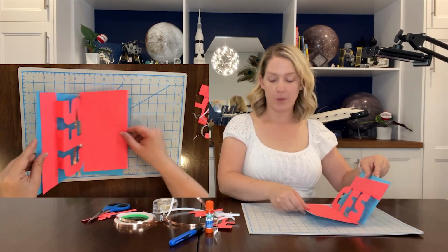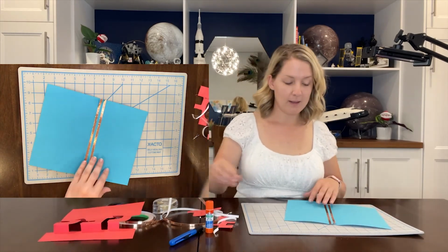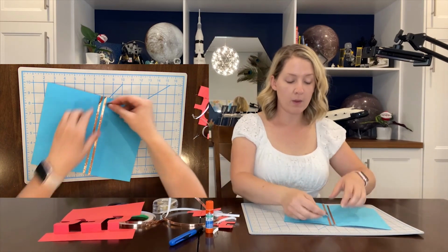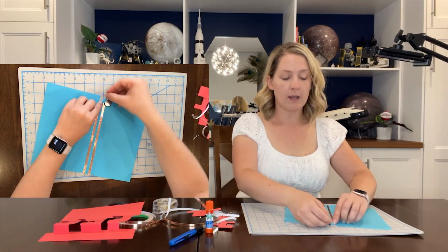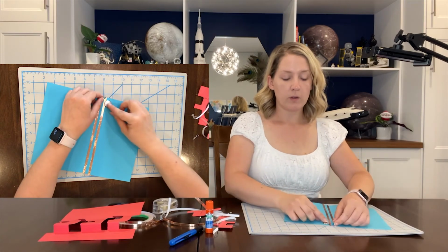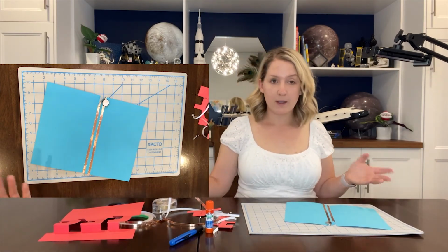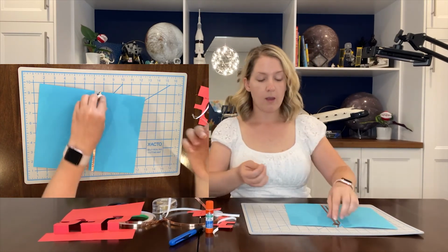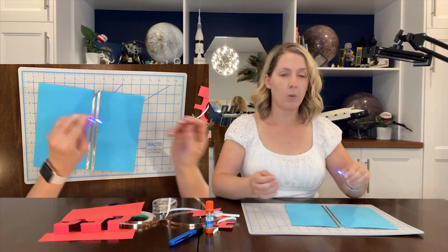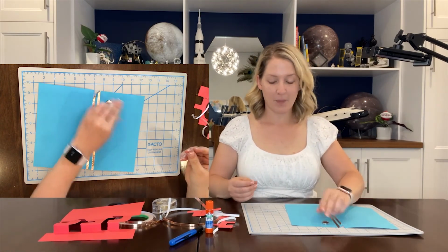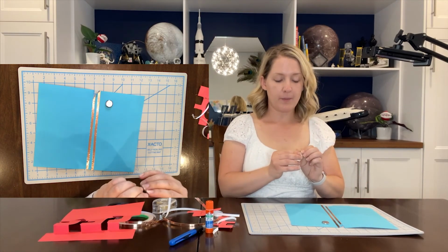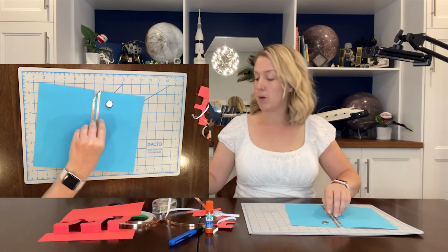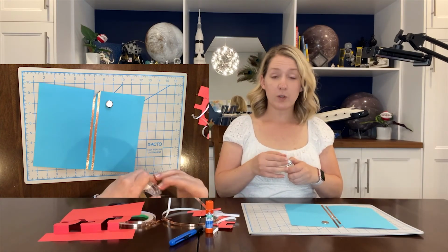So now that we know where the letters are located, we can place the LEDs on the backing page. So with LEDs, what I would recommend is decide which way you're going to have your battery. I like to have the positive side down and then the negative side on the top. So I can even leave a little note to myself, or you can have students write positive on the bottom, negative on the top. And then of course you would check that your LEDs are all working before you place them in. Here we'll just bend the legs of the LEDs, and we'll place the positive terminal on the bottom. Those will just tape down.